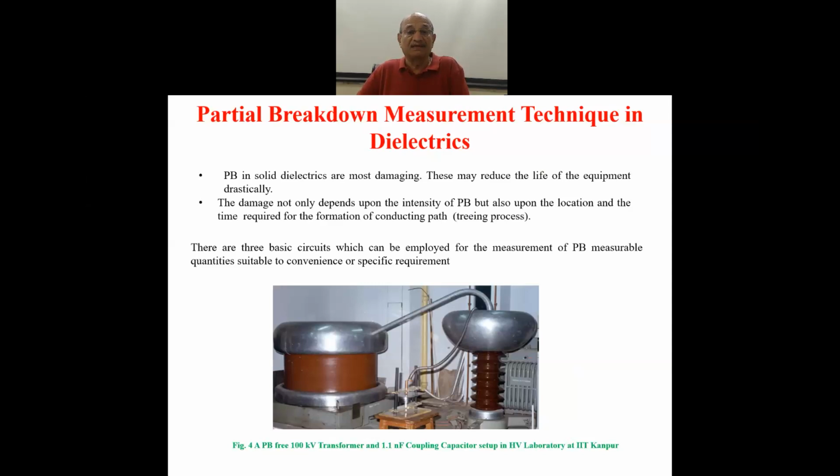But in the case of liquid dielectrics, as in gaseous dielectrics, the dielectric may get replaced near the electrode where the partial breakdown is taking place, that means at the maximum field intensity in the electrode system.